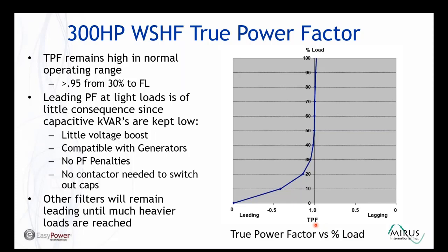So here we're showing true power factor, leading on the left side, lagging on the right side, and we can see that 0.95 or better, we're at that level at about 20% loading and above. So we're near unity power factor over a very wide range on the filter.